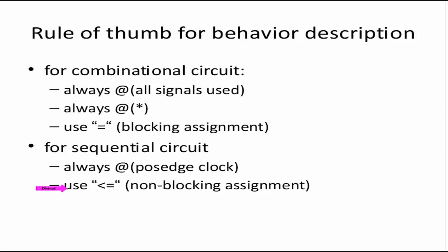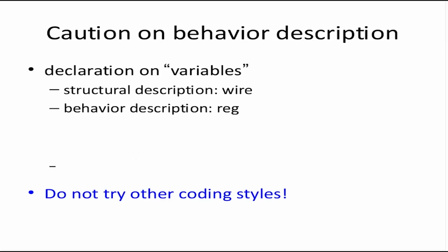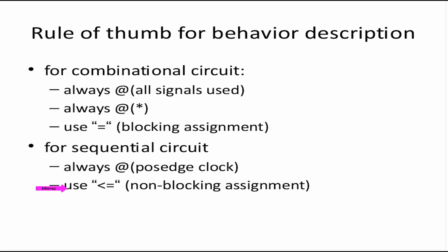So we saw the case of writing combinational logic. We saw that we could use an always block or we could use the assign statement for writing combinational logic. We saw how we could use always for writing sequential logic. We saw in what case the tool tries to implement a latch, and it is our duty as an RTL designer to make sure that latches are only present where intended.